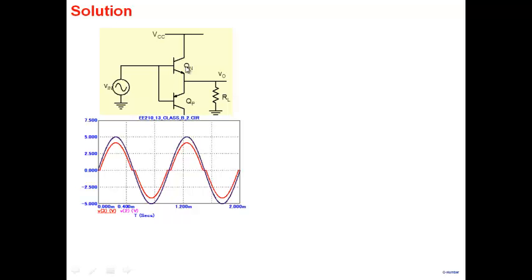When the input voltage comes, it adds a little bit of voltage and it turns on. So I don't have to apply 0.7. There's already a 0.65 or so applied to QN. And similarly, there's already a minus 0.65 applied to QP. If that is there, then when my input comes in, it will quickly turn on. It doesn't have to wait for 0.7 volt, and thereby distortion would fall.